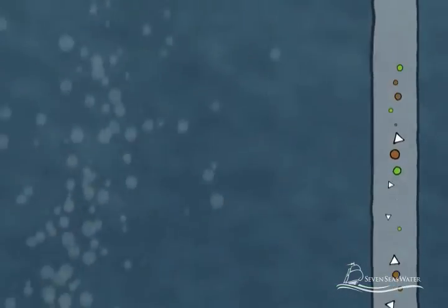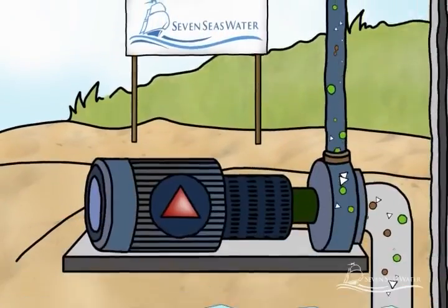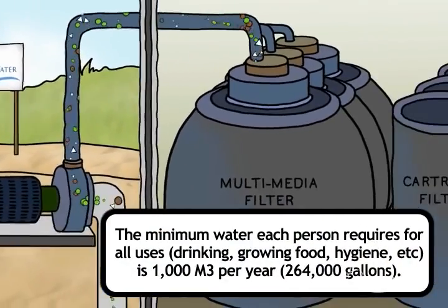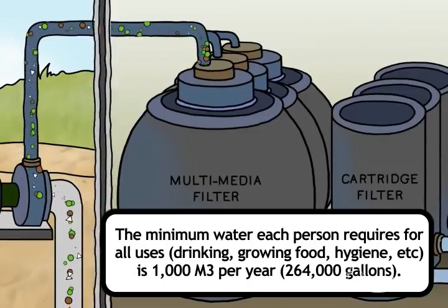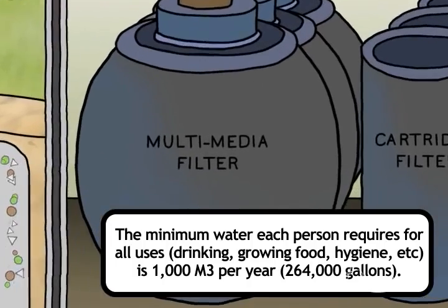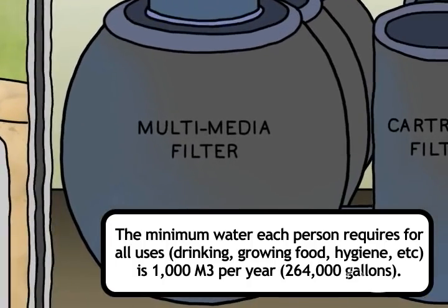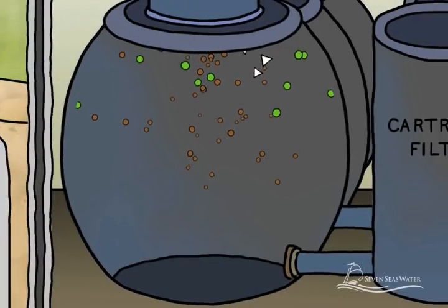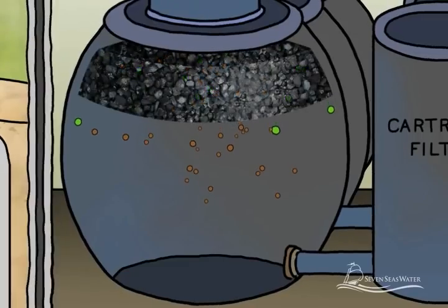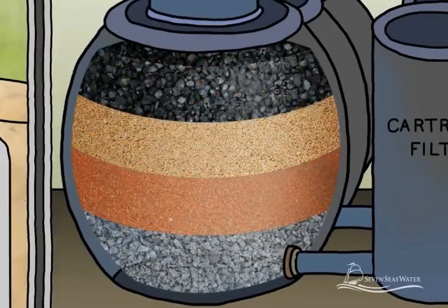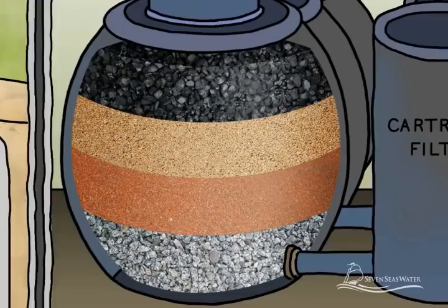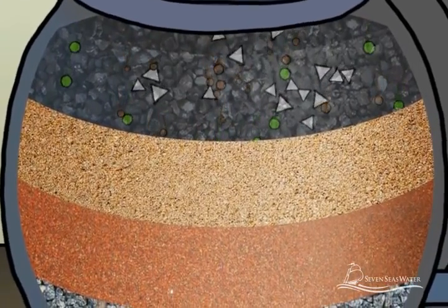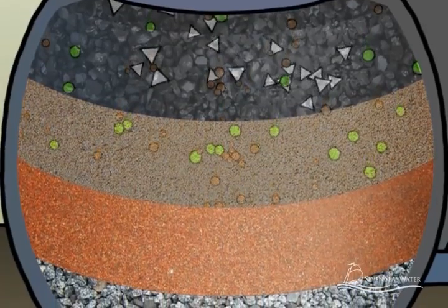To protect the reverse osmosis membranes from becoming clogged by solid particles that can be suspended in the seawater, the seawater is filtered before passing through the membranes. This is accomplished by using multimedia filters, which are tanks or vessels containing a series of layered granular materials. These materials can be anthracite, garnet, sand, pebbles, and/or gravel, which are assembled in layers. The filters remove sand, twigs, seaweed, and other particles from the seawater.